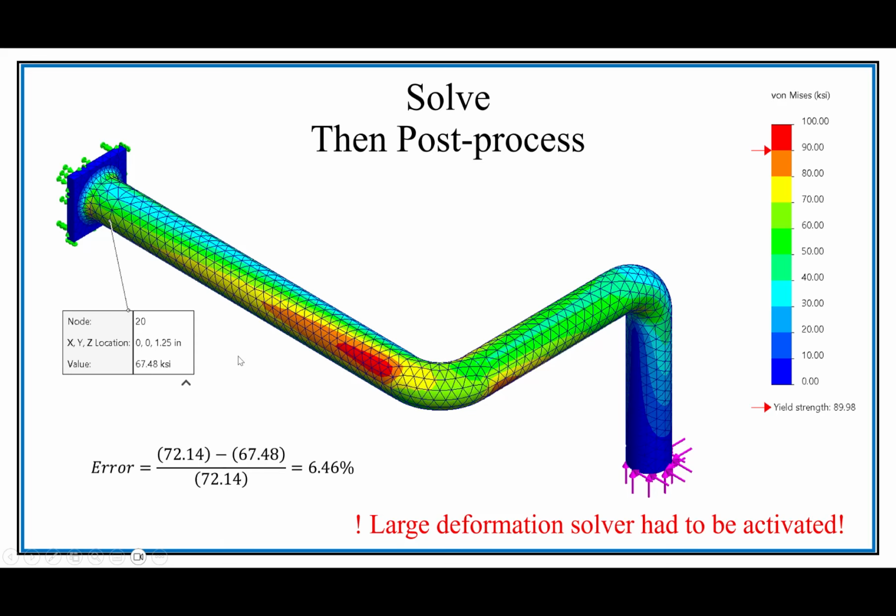I'd say definitely. I don't know that for sure, but by making a finer mesh in the location where I care about the stress. I'd also point out that as I'm solving this, I get a warning that we have a large deformation. I had to use a different solver. So some of that 6.46% difference could be because of the mesh, but it also could be because the loading condition is so large that it's actually not a linear solver anymore. The hand calculations that we're using were based more on a linear approximation.